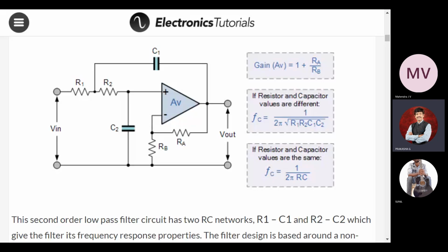So on these two, plus 15 volts, minus 15 volts. Pin number 2, pin number 3, pin number 6, 7, 4 with respect to the mu A741. Kindly note down. Do it fast. And we will be having V0 also. Vin has been given, and we will be having V0.